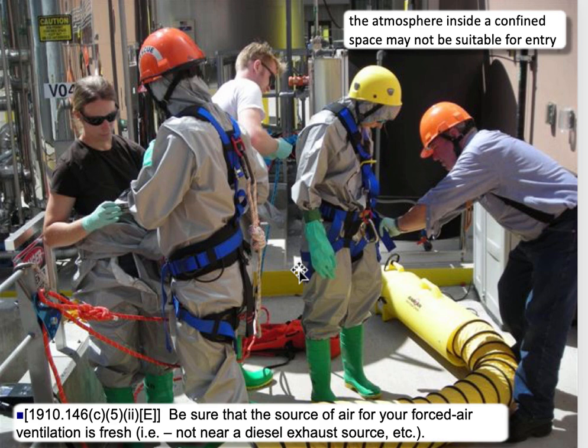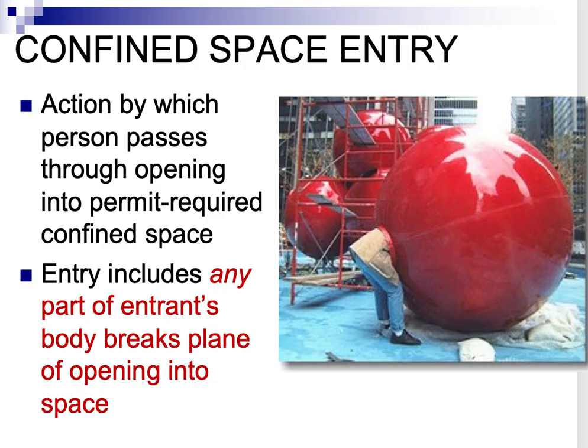And so this is just a great picture of confined space entry. You can see these people are wearing climbing helmets, not hard hats. They have fall protection equipment on. It looks like they're in level C. Nope, level D clothing, they're protected without protecting their faces here, so this would be level D clothing. You have backup people as well as a supervisor who's assisting with the job. And so a great example of confined space entry where you're going into a tank of some form.